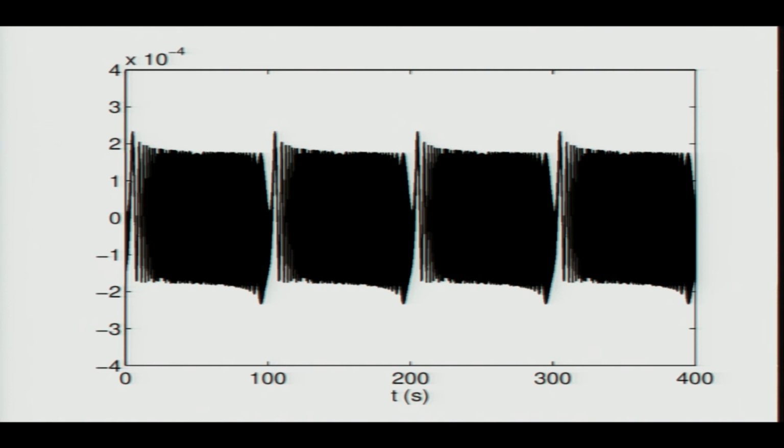I can excite the linear circuit with this kind of multi-sine signal, obtain the response, and thereafter take the Fourier series of this signal and also of the output signal and get the frequency response.